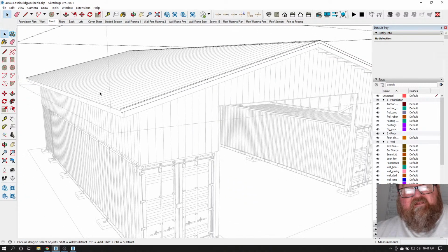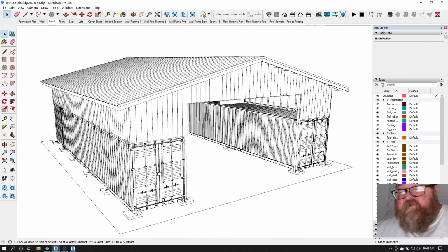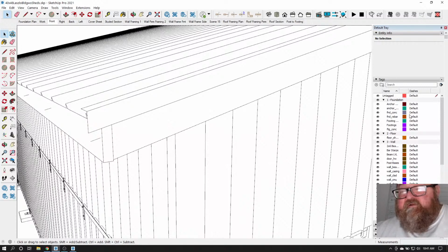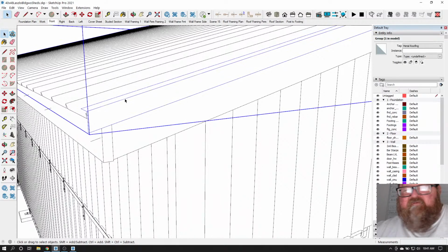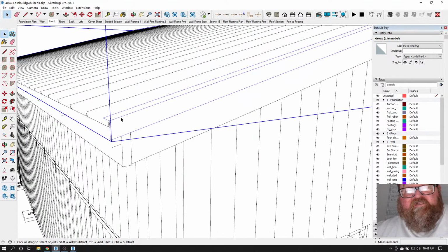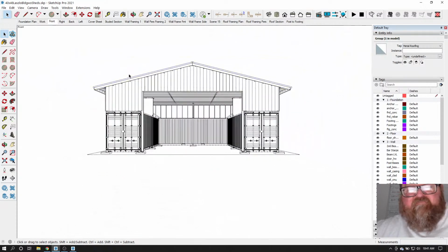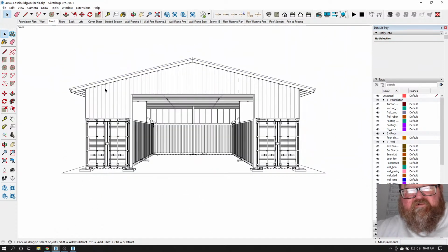In AutoCAD, you could set up your colors as a line weight. Typically we would set red as 0.5 and black as 0.25 or whatever, and then you would just know to make this line red. Depending on what architecture firm, sometimes they'll have their own CAD standards.